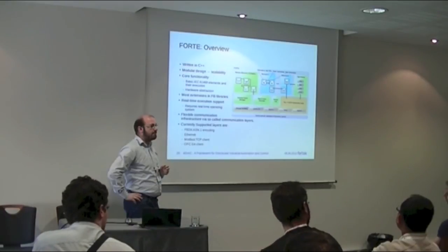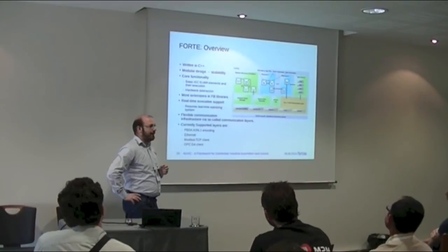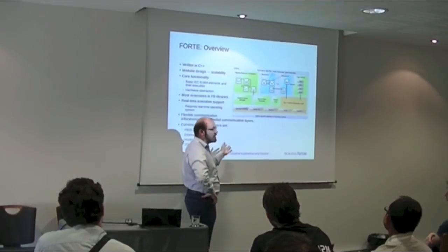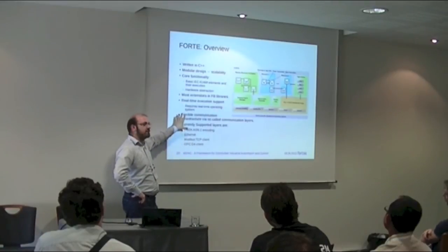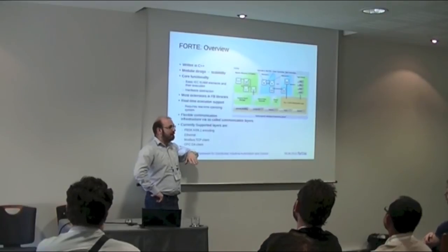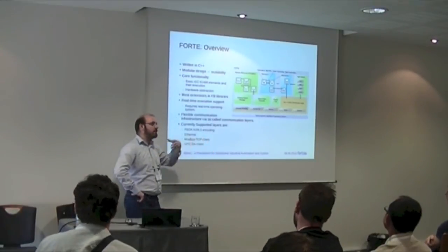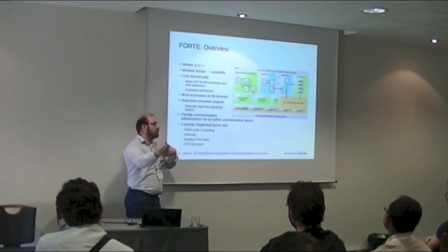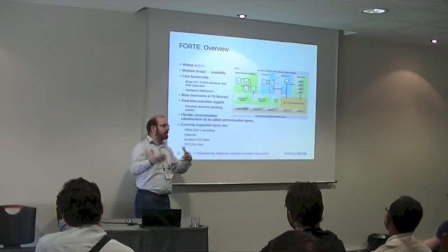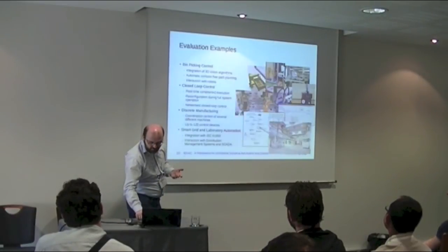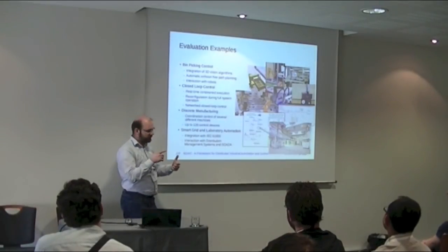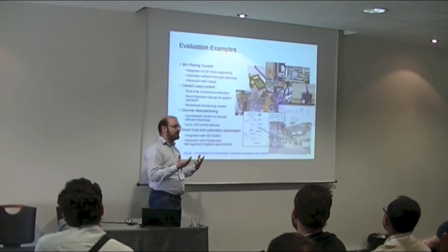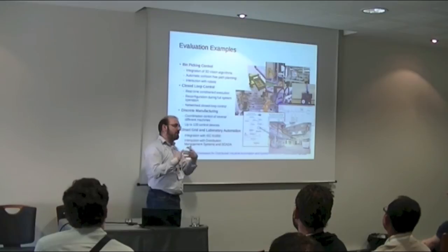And on top of this layer, you implement something like OSGi remote services? Could be possible. Maybe not OSGi, but other services could be interesting to implement. There are certain features in 4099 which I could not present today because of time, which could easily allow you to define interfaces to the network, like a service kind of interface, which could then be invoked by others, especially if I want to coordinate a set of machines. There are many standards out there, like IEC 61850, which is for smart grids, or OPC-UA, or other service mechanisms that define how the interface of such a device should look, but nobody is talking about how to implement them. This could be an option for implementing it in an industrial way.